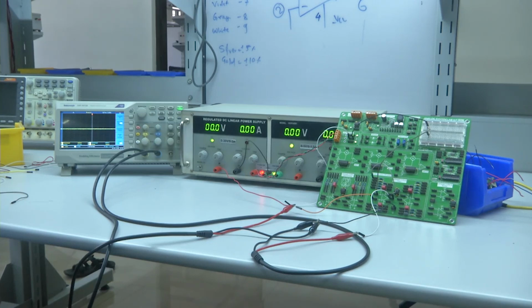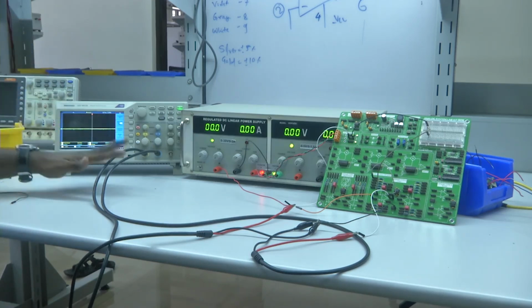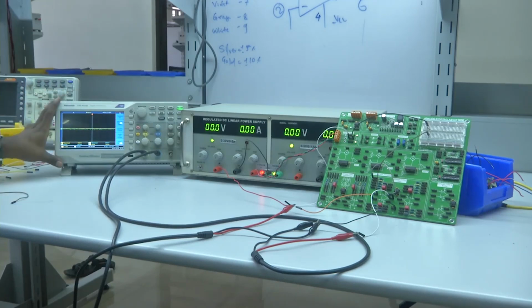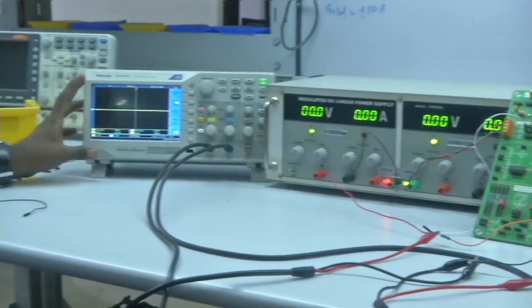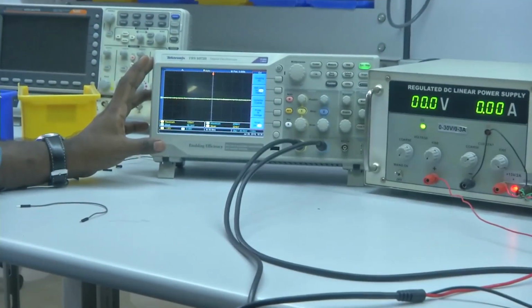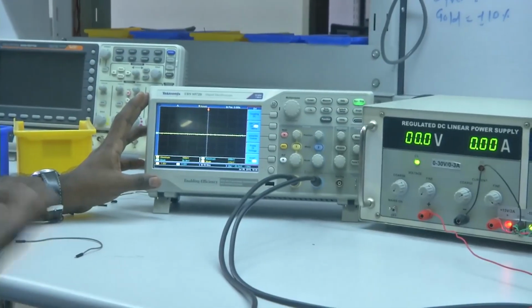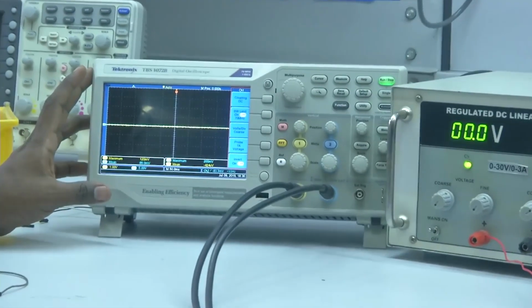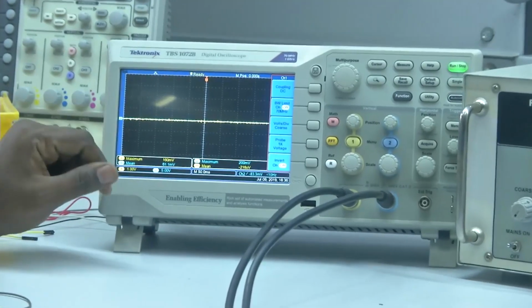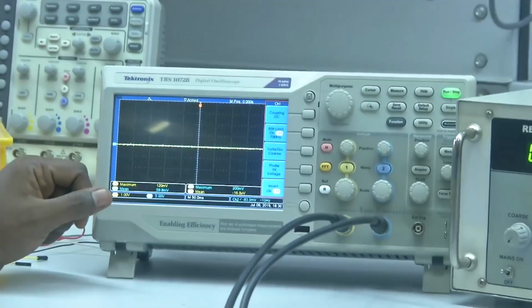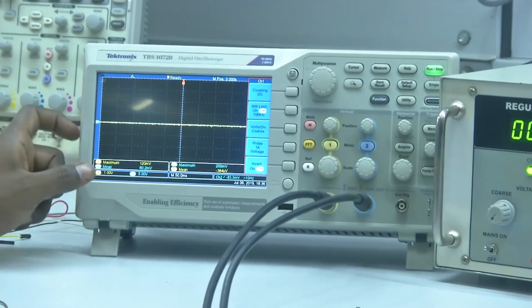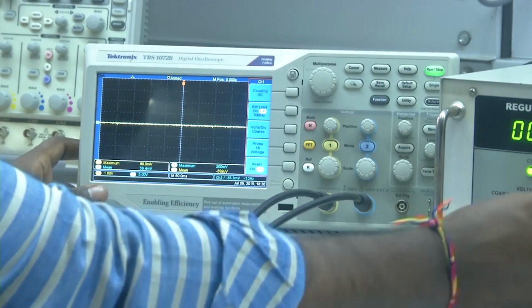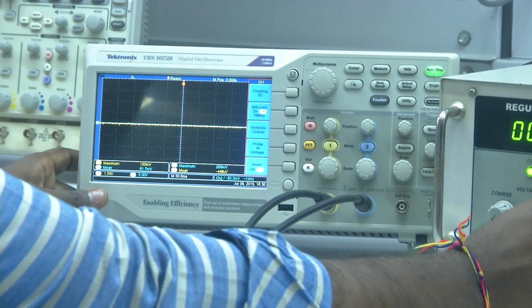Let us see the working of the board. Right. So, let us focus on the oscilloscope. We will try to increase the input voltage in steps of 100 milli, 200 milli, 500 milli and 1 volt, the same way as we saw previously in the inverting amplifier configuration, and we will observe how the output is also changing. The output divided by input gives you the gain, and we will calculate the gain. So, let me increase the input voltage.